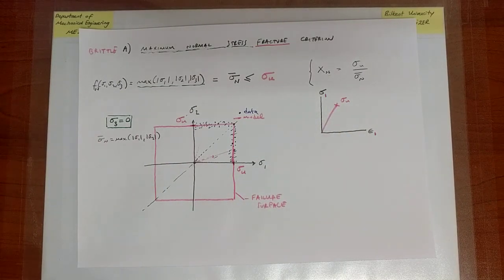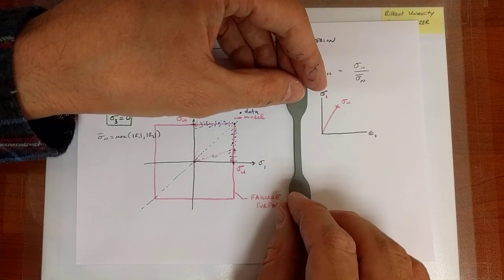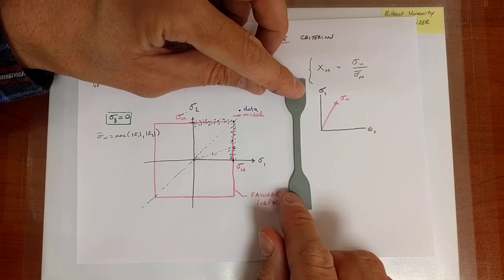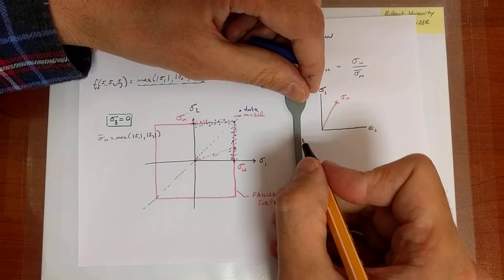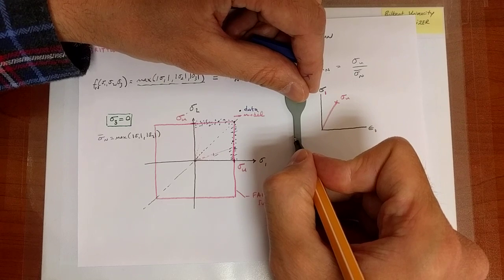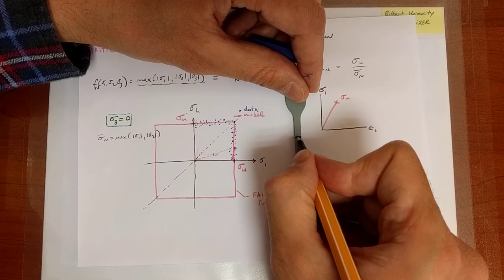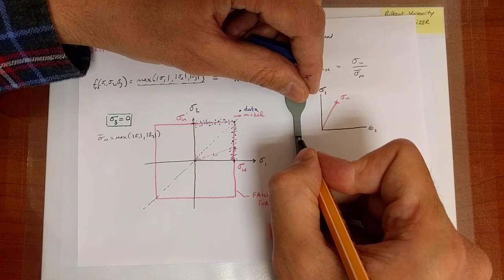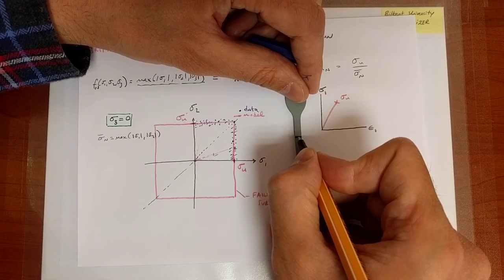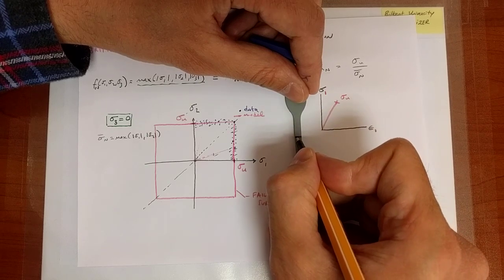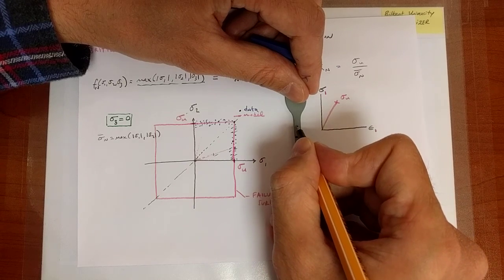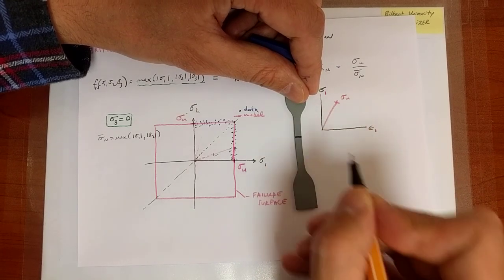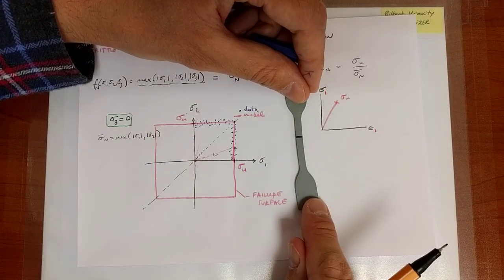Which means that when I do a uniaxial loading test with a specimen, this is a rubber specimen, but nevertheless, let me take it. I pull on it and the specimen will break when I reach the ultimate strength of the material. Well, the plane that is associated with the ultimate strength is essentially the plane that is normal. This is the plane. The normal stress is in the normal direction to this plane, and therefore that stress is exceeded. When that stress is exceeded, the material fails in a brittle fashion, which means it will fail along the plane on which you have maximum normal stress. So I expect the fracture surface to look like this if this is a good criterion.